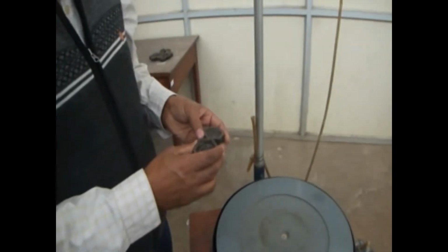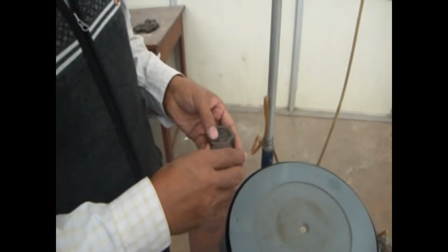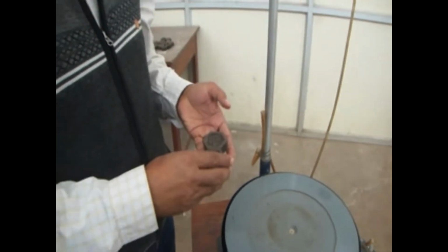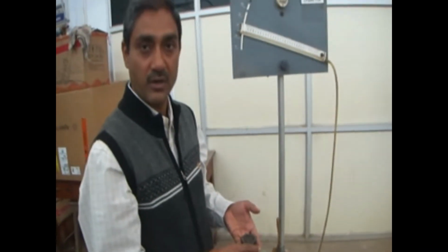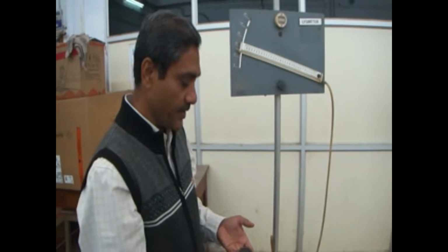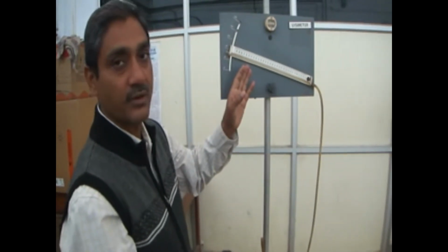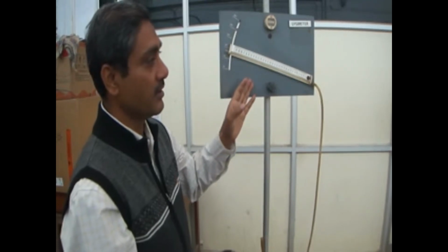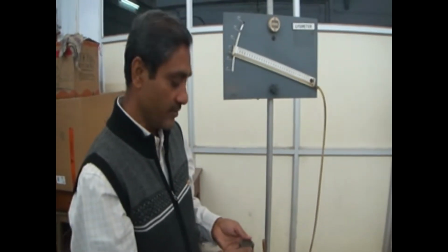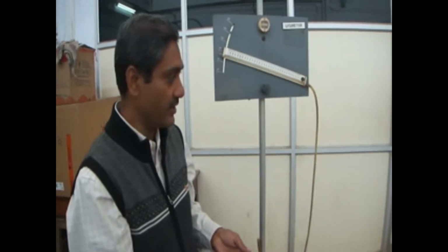So once we are putting the 200 gram weights, it is simply resembling the addition of irrigation or rainwater in the field, and we are observing what is the head. So that is simply the weight. When we are removing the weight, it will give us an idea of the water loss from the system because of evapotranspiration. That is our target here.